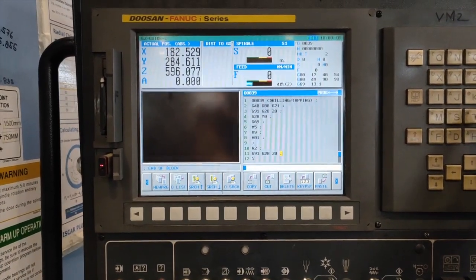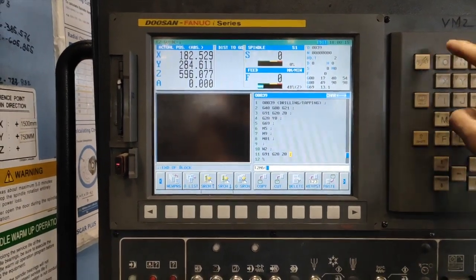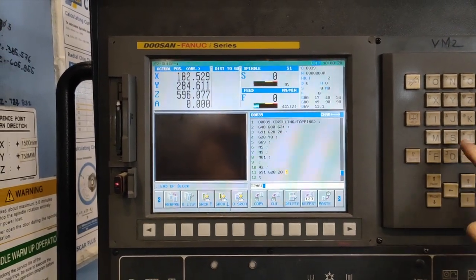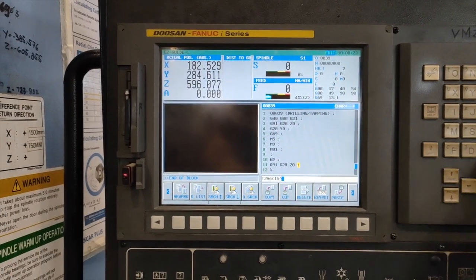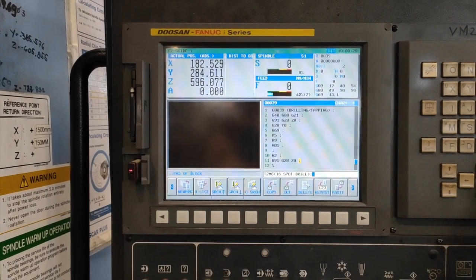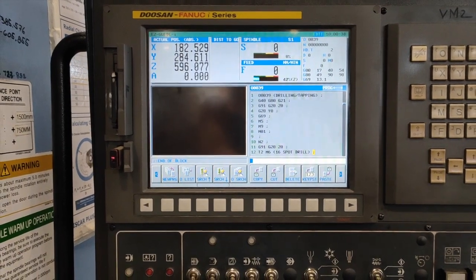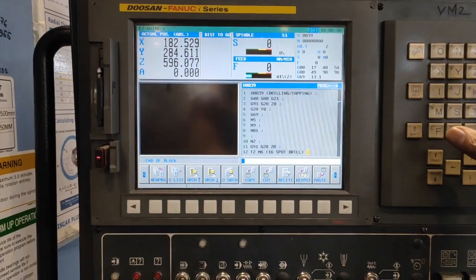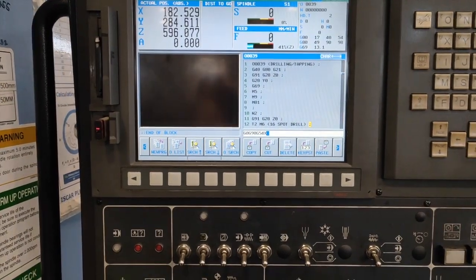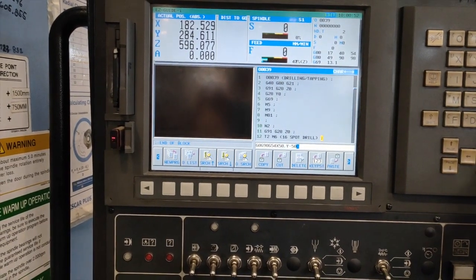And I will follow with my tool number 2, M6, and I will use a diameter 16 spot drill, 16 spot drill, in a block, insert. And I will position to the first hole, G0, G90, G54, X. Let's say the position of my hole is 50 on X and minus 50 on Y.